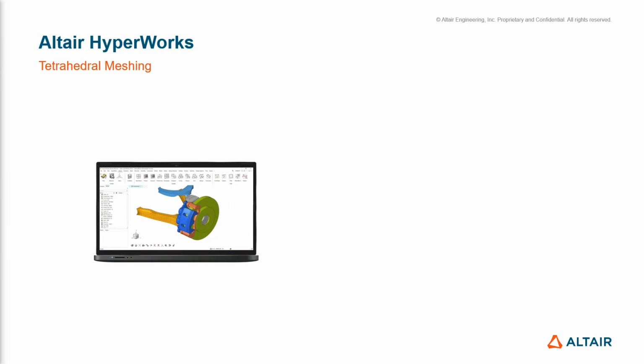We offer quick and easy workflows for tetra meshing with methods appropriate to your requirements and meshing standards. The first method is accessing the tetra tool in the mesh ribbon, where we can quickly generate tetra mesh from closed volumes of shell elements or from solid or closed surface geometry. We can also quickly remesh to regenerate and refine particular regions of our models.